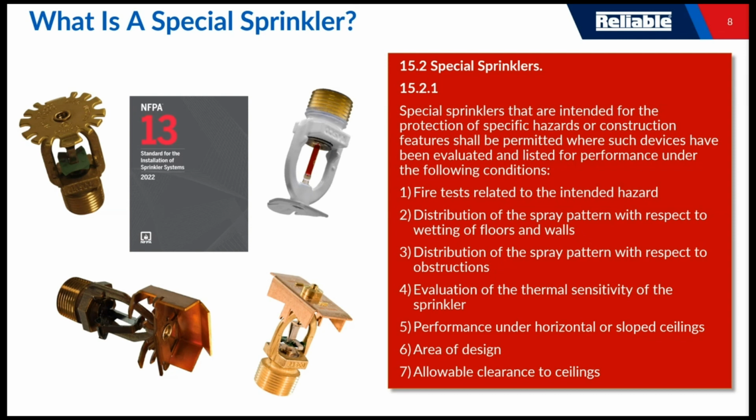Evaluation of the thermal sensitivity of the sprinkler. We've got to know if it's going to become a quick response sprinkler or standard response sprinkler. Performance under horizontal or sloped ceilings. The area of design. We make a new sprinkler, we've got to tell you how to calculate that. And then the allowable clearance to ceiling. So where do we position that sprinkler with respect to something like a ceiling that might be able to collect heat and activate the sprinkler?